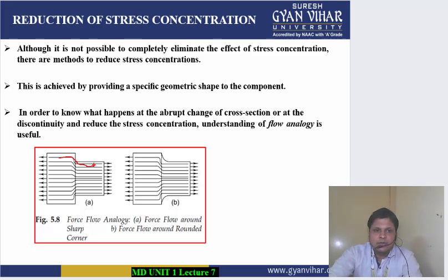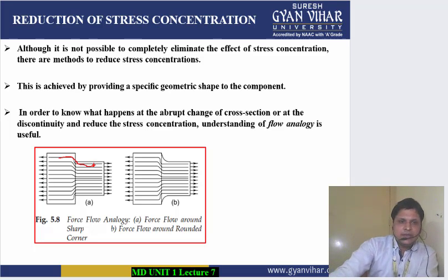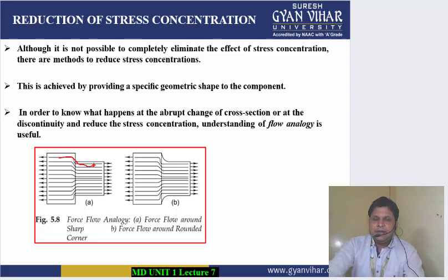At the change of the cross section, the streamlines as well as the stress lines have to bend. When there is a sudden change in cross section, the bending of stress lines is very sharp and severe, resulting in stress concentration.